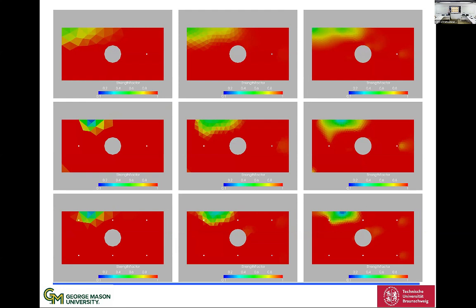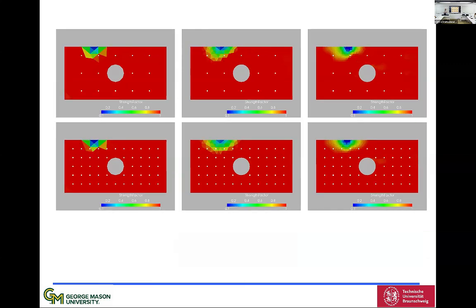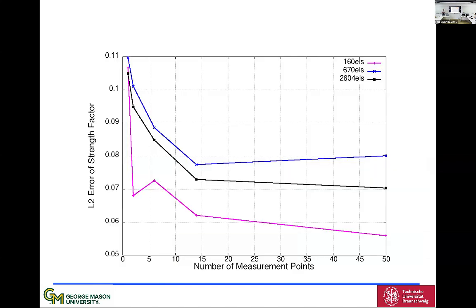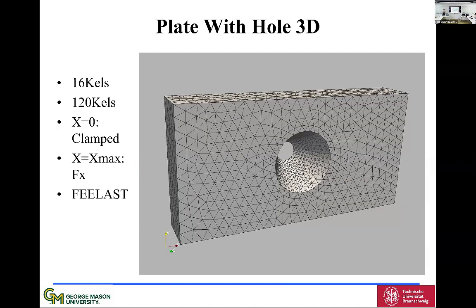In some cases, the coarse mesh, if you were to measure the actual error, the integral of alpha minus alpha exact squared d omega, is actually less than what you get on the fine mesh, but the fine mesh gets a better value in the end. So this is, again, the coarse, the medium, and the fine mesh. And you can see in all cases you recover the region, but it's not perfect. Okay, so this is just the convergence curve for that.